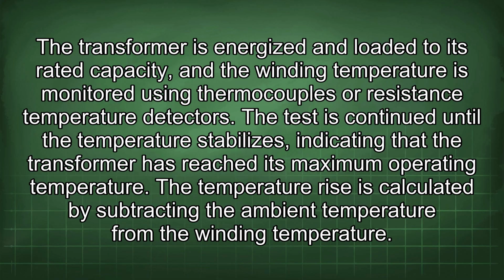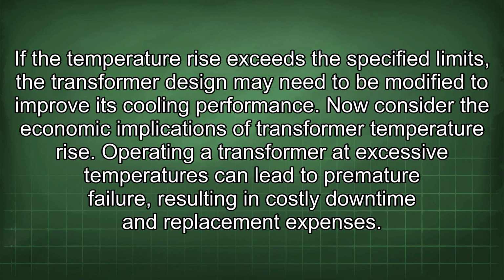The temperature rise is calculated by subtracting the ambient temperature from the winding temperature. If the temperature rise exceeds the specified limits, the transformer design may need to be modified to improve its cooling performance. Now consider the economic implications of transformer temperature rise.